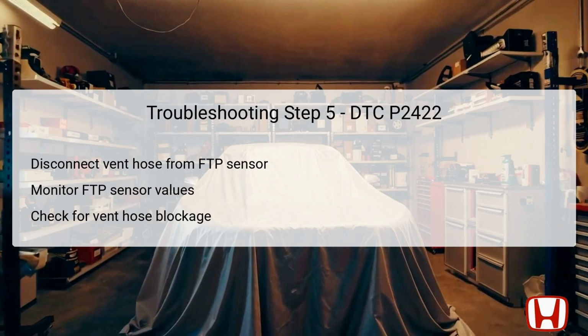If the values meet the requirements, a further investigation into the vent hose for potential blockages is warranted. If blockages are suspected, they should be promptly addressed to restore proper airflow in the system. Resolving such obstructions plays a vital role in the full functionality of the EVAP system.